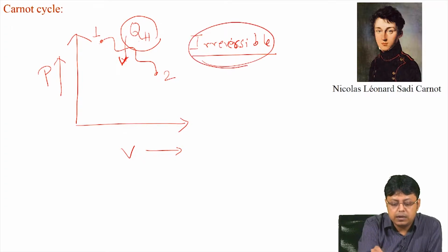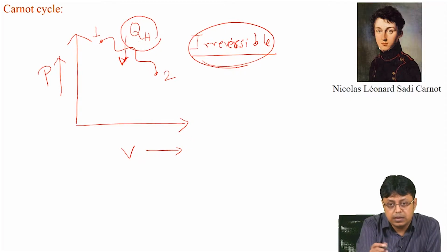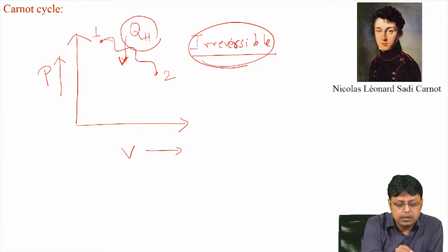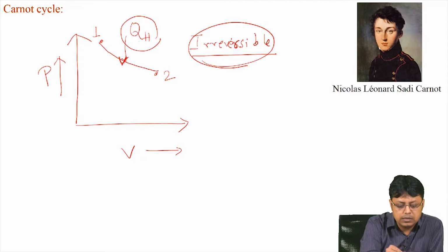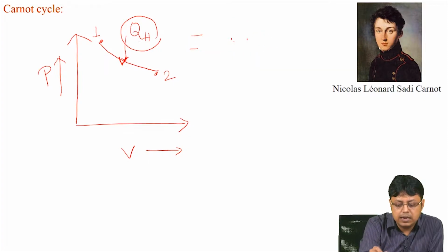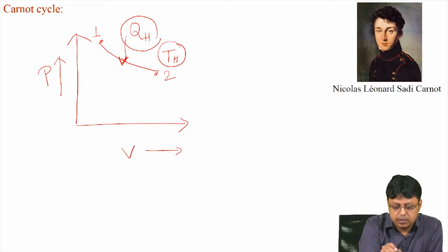In order to maintain reversibility, because we have to maintain it, remember, because the system has to be restored to its original condition, then we assure one thing, that this path has to be an isotherm. So, this cannot be a wavy line as we have drawn here. The first part has to be some isotherm where the system withdraws heat from the surrounding, which is the hot reservoir, keeping at the same temperature as the hot reservoir.